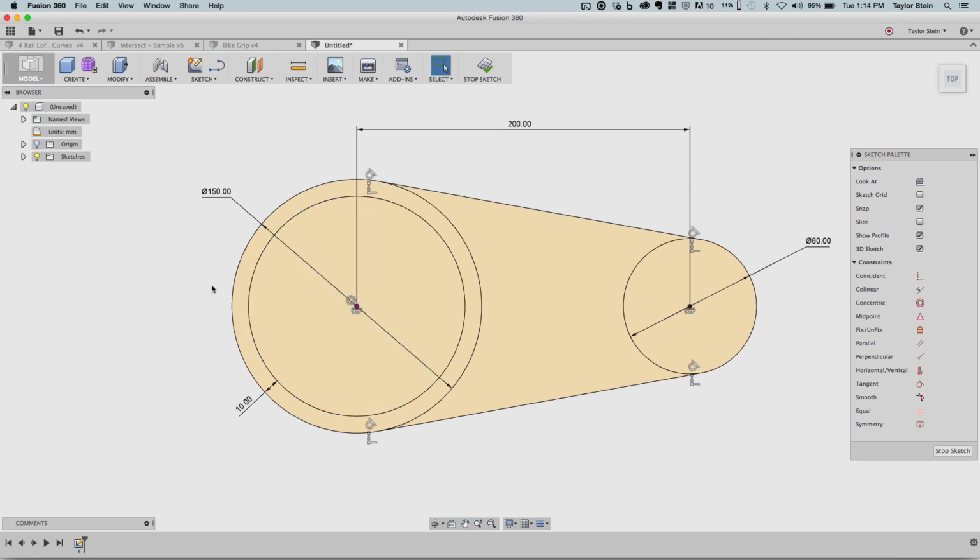I want to actually draw some lines over here. So I'll start the line command. I'll start it over here, and as I move across, I'll add a coincident constraint here to this inner circle, and we'll see that we also have a horizontal constraint. So this line is horizontal, and its other end is coincident with the inner circle right here. I'll draw another line down. We'll have a perpendicular constraint, and now I can draw it horizontal and coincident with that inner circle.